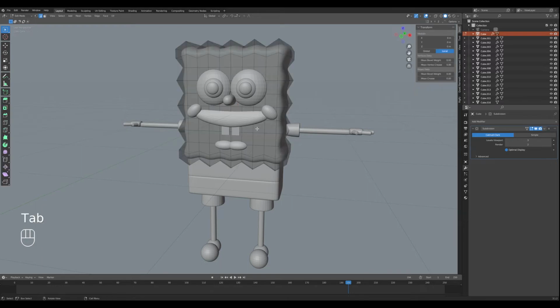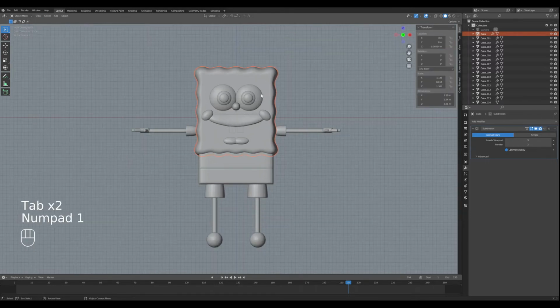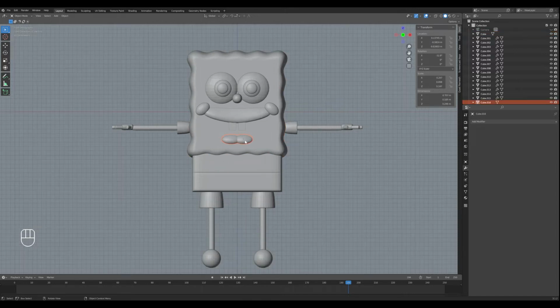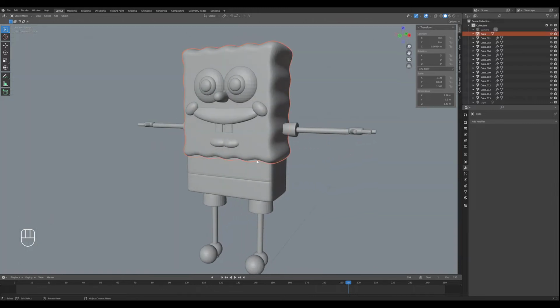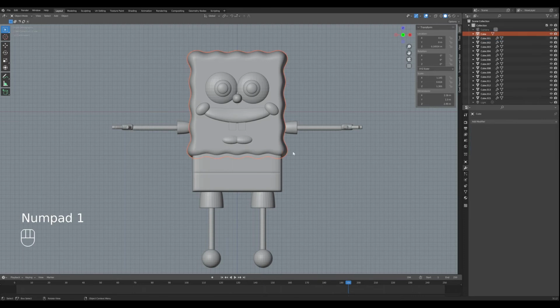And you know what, since we're happy with the body, the curves, the little dips on the sides and the top, we can go ahead and apply this modifier as well. So Control A, because we need to apply all the modifiers in order to join two or more objects, or else it messes up. So click the chin, then hold Shift and click the body. So there's two selected, and then Control J to join. See, it gets rid of this curve here on the top, and it looks more like one.